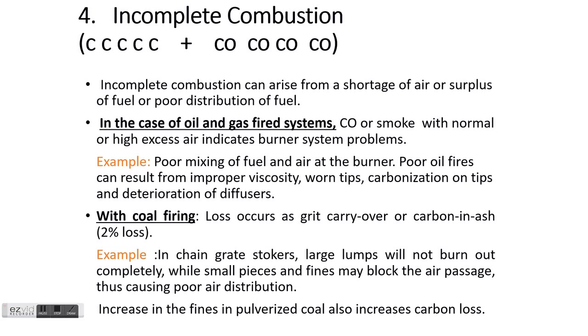In the case of oil and gas-fired systems, CO or smoke, for oil-fired systems only, with normal or high excess air indicates burner system problems. A more frequent cause of incomplete combustion is the poor mixing of fuel and air at the burner. Poor oil fires can result from improper viscosity, worn tips, carbonization on tips and deterioration of diffusers or spinner plates. With coal firing, unburned carbon can comprise a big loss.